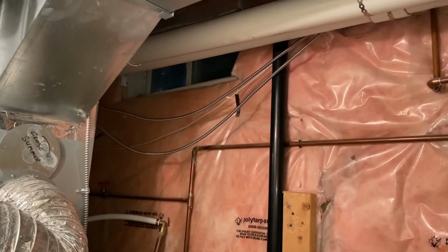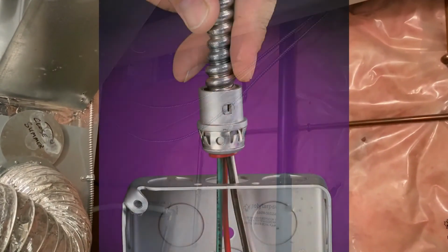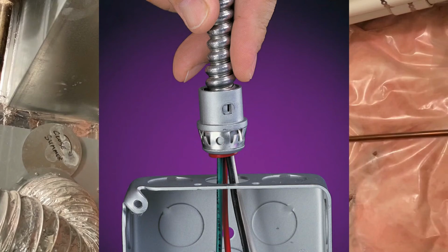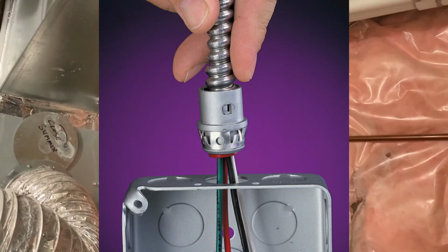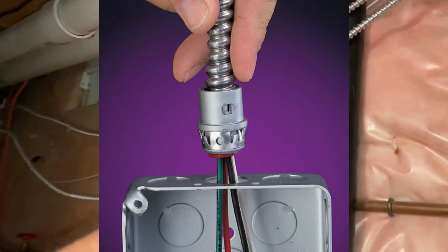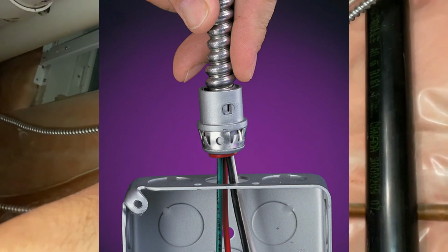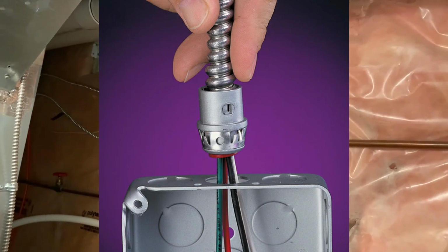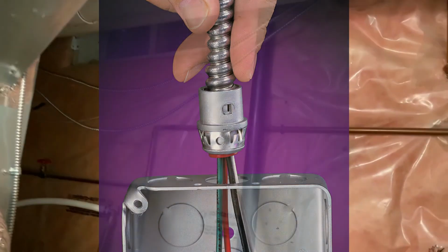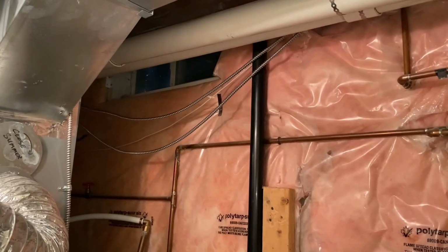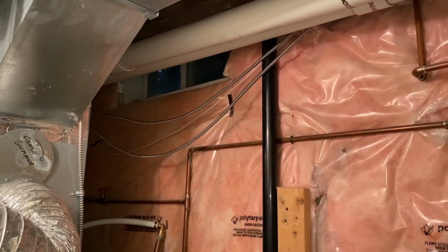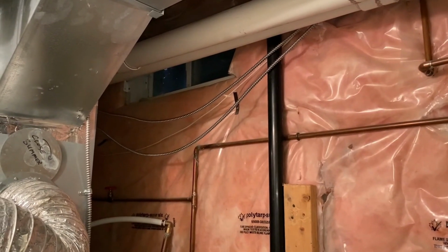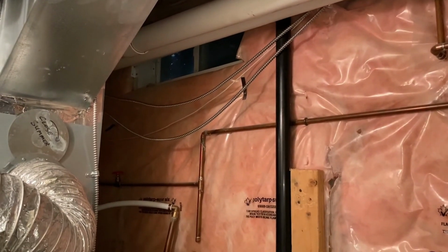But when this cable goes into one of the electrical boxes, whether it's for your pot light, your switch or receptacle, doesn't matter, this cable will be clamped to that electrical box. And that electrical box is always grounded. By code, we have to. So this cable with that conductive jacket is always maintaining that ground connection.